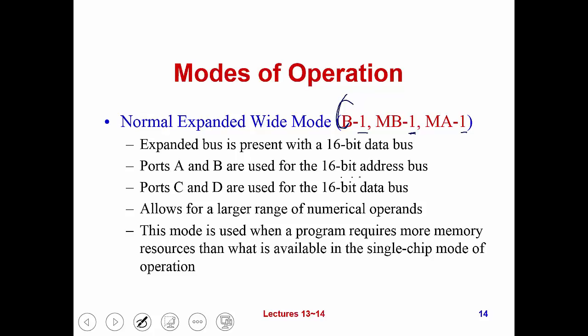So in this case, it allows a much larger range of numerical operands. This mode is designed for the 68HC12 to work with a program which requires much more memory resources than is available in normal single chip mode. That's why I call it expanded wide mode. Address 16 bits, data 16 bits.